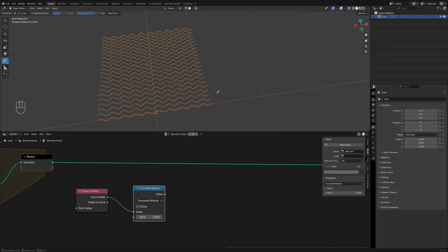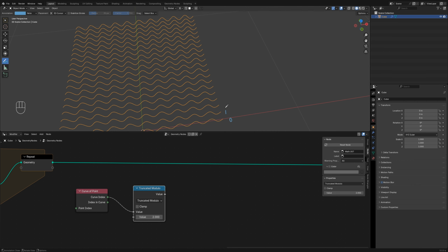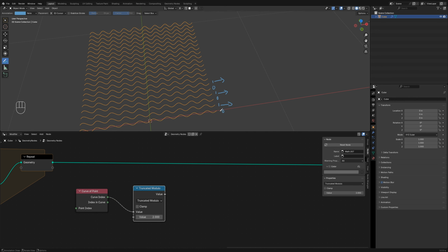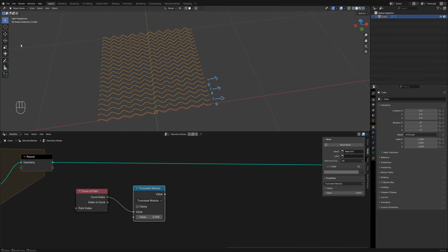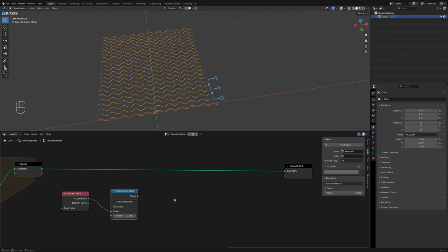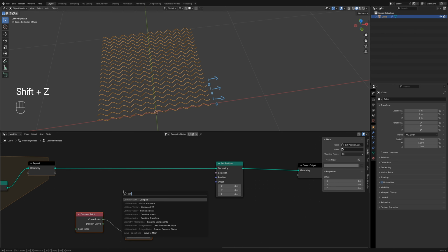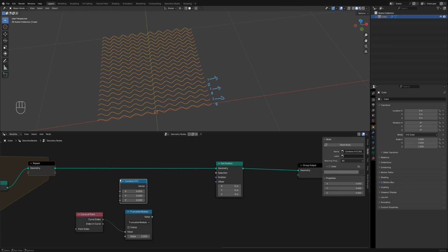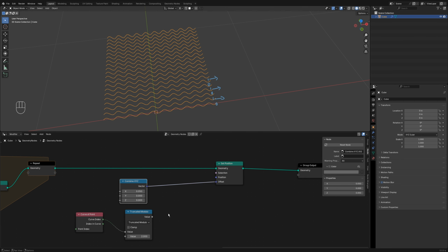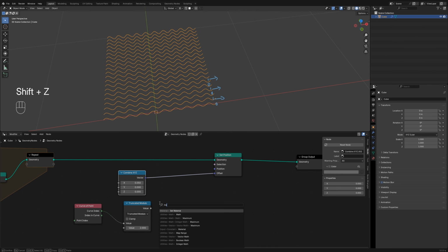We can multiply the offset value by the modulo result, thus achieving precise staggered offsets. The specific offset value should also use my previously set green node. I forgot to connect it. Ensure you connect it.